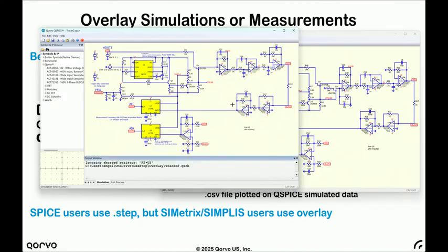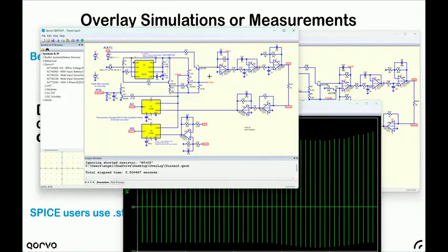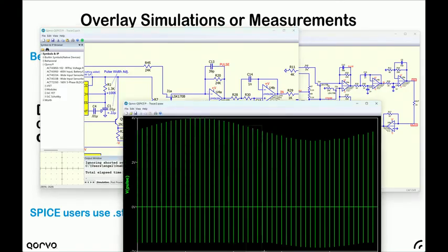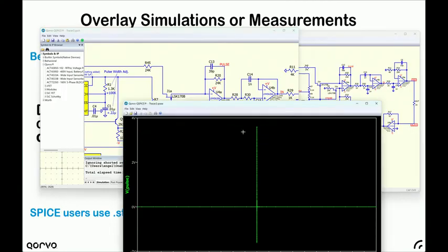We'll run this simulation. Now the way I do the pulsing is a pretty standard idea. I use a JFET working into the virtual ground of an op amp. JFETs are usually used here because they'll have less charge injection for the same RDS(on) as a MOSFET. Standard technique. But if you get to like 10 microsecond pulses, let's look at what this thing looks like.